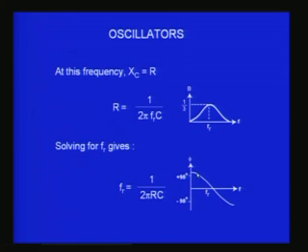With frequency on the x axis, at that frequency the phase goes to 0; before it is plus 90 and beyond it is minus 90, so in between it crosses 0. When it crosses 0, the corresponding feedback ratio is 1 by 3, and that gives me an expression for the frequency as 1 by 2 pi RC.